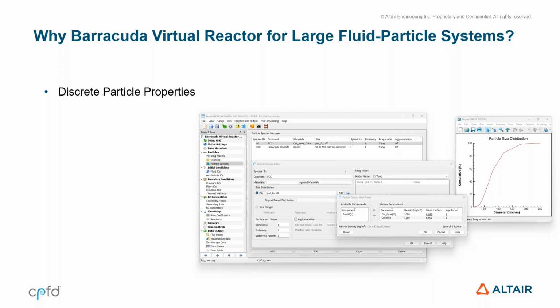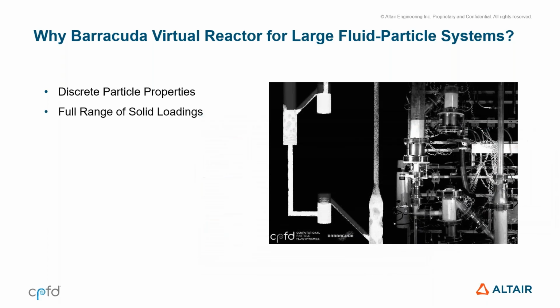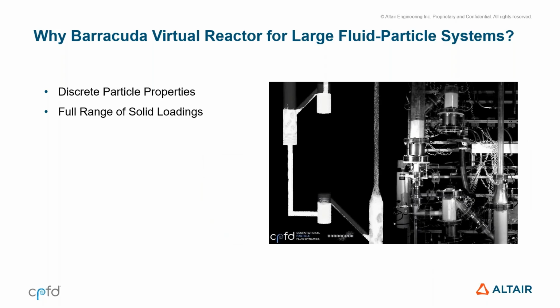And so with Barracuda Virtual Reactor, both on the inputs, whether it's a particle size distribution or other discrete properties, composition as we're showing here, and not just on inputs, but throughout the calculation, the evolution of things like size, composition, temperature, history, residence time, all is on a discrete particle basis. So every particle has its own behavior.